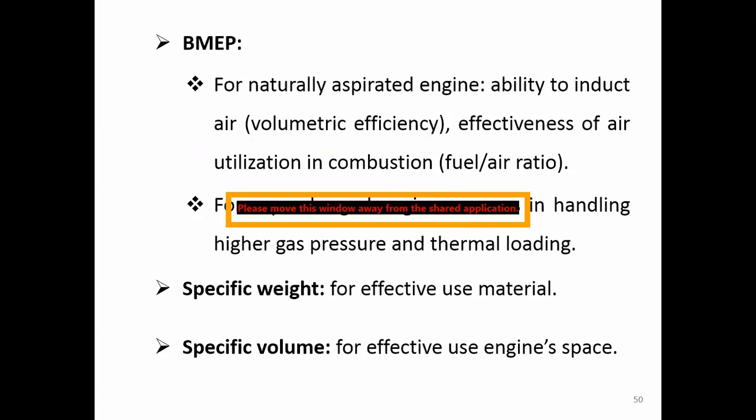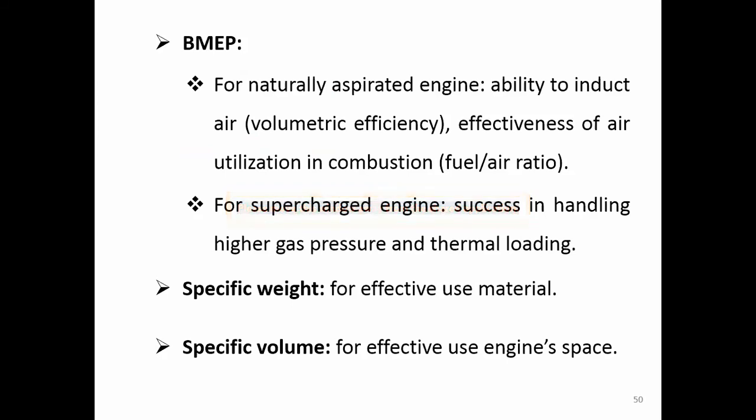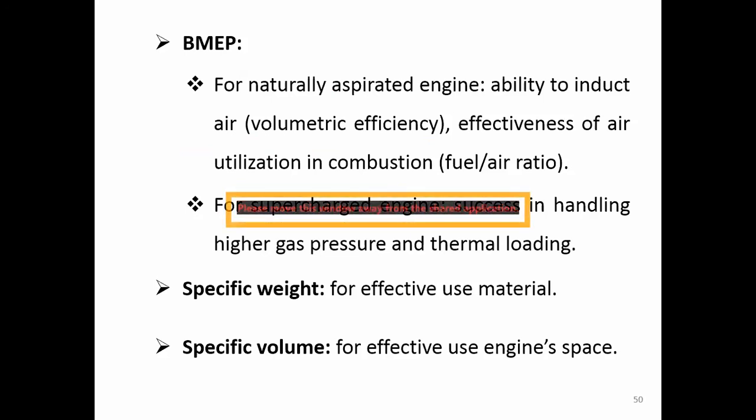We measure also the BMEP, right? Because we want to see that if we design a naturally aspirated engine, we want to look at the ability of this engine to intake the air, which is represented in terms of the volumetric efficiency. We want to look at the effectiveness of the air utilization in the combustion, which we look at through the fuel air ratio that this engine can receive.